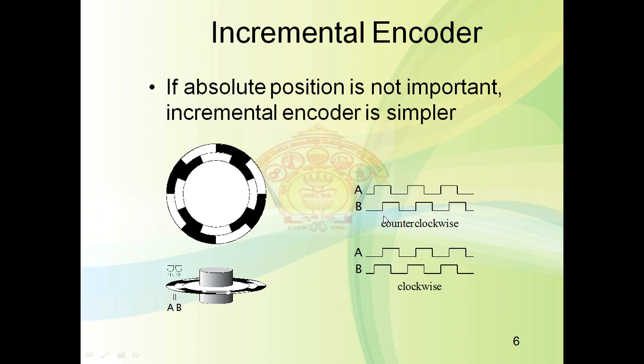So it can rotate in the clockwise direction and the counterclockwise direction. If it is rotated in the clockwise direction, then you will get A lagging and B leading. Likewise, you will get the output here.